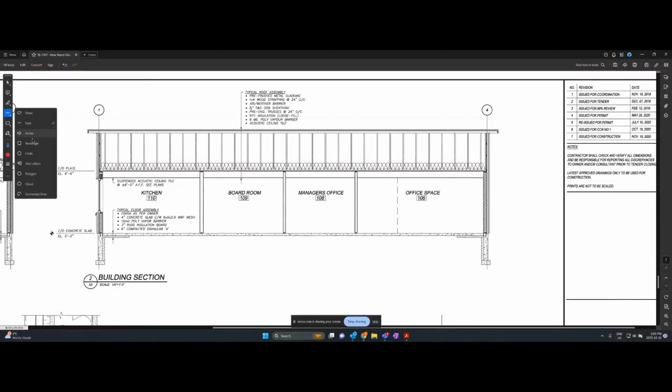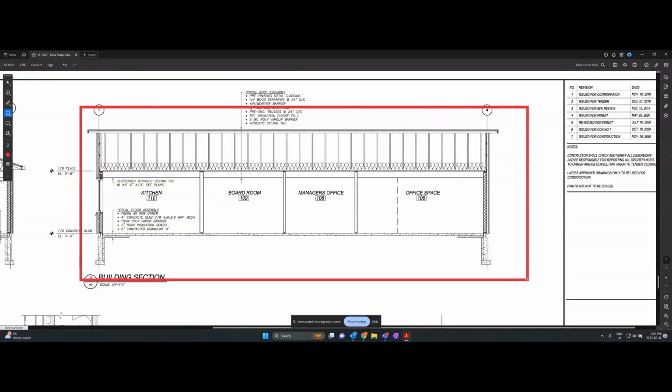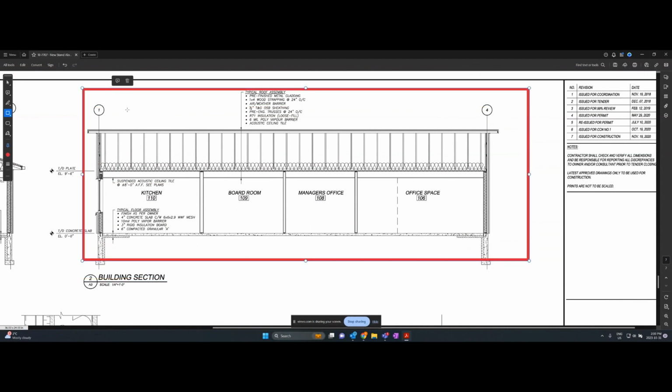And as you can see here, we have a nice section of a building. So we're looking through here, we have an acoustic ceiling tile. So there's your SPD right there, okay? Then we have an air gap, and we have 6 mil poly, insulation, engineered truss, sheathing, and everything, but it doesn't show drywall. There is absolutely 100% drywall being installed here, and we'll find that later on when we're going through everything.